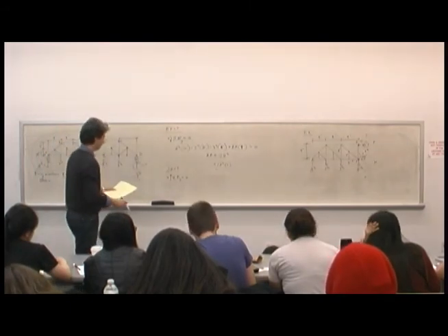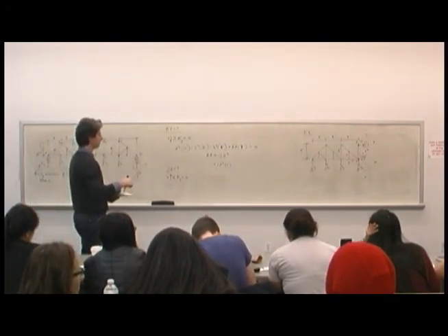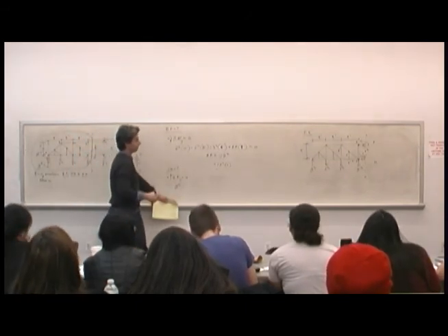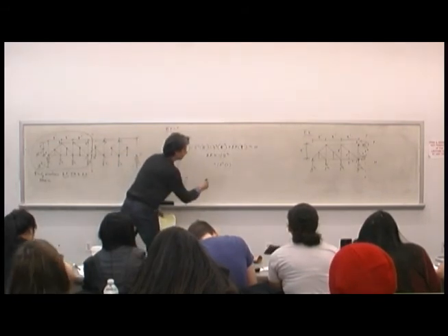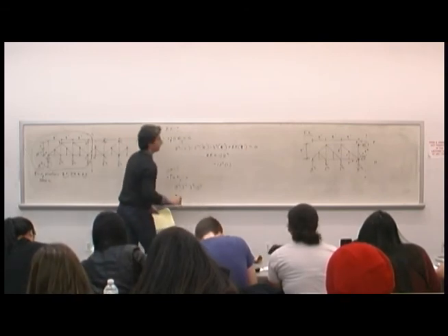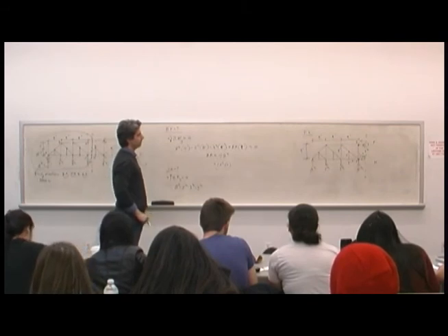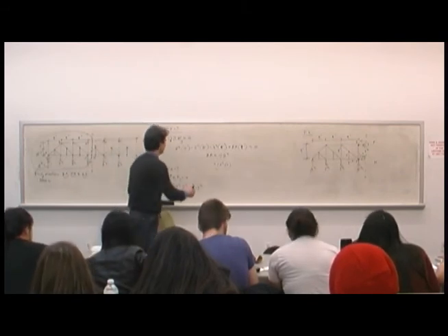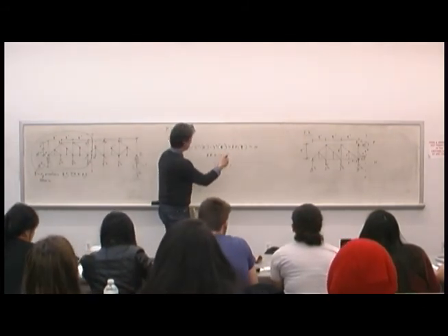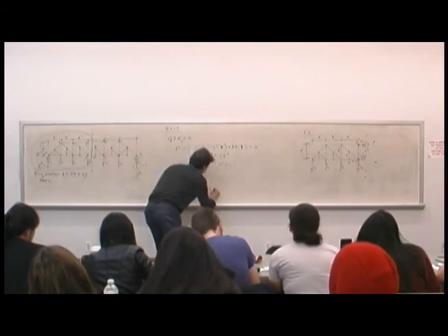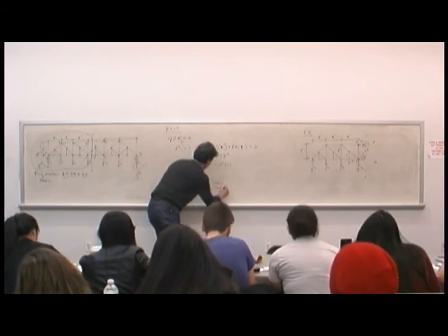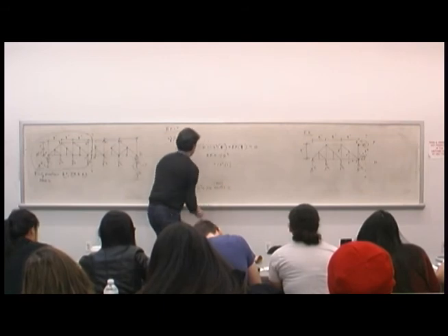How do I balance it? What's the 8 doing? Positive, negative? Positive, so it's 8 kips. The 2 kips is what? Negative. The 3 kips? The 5 kips? Okay, what's the vector then? JK what? Is it positive or negative? Based on that, positive. Positive JK cosine 45, which is 0.707, right? This is equal to 0. Solve for JK.